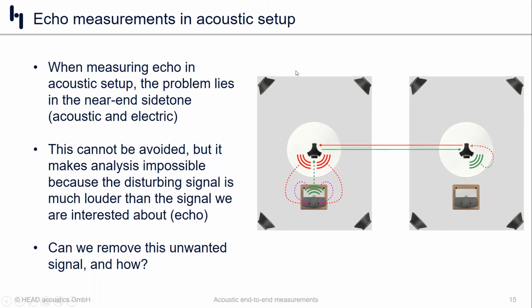So in this case, for the full acoustic end-to-end, we have 2 chambers set up. The process is the head and torso will speak, that's shown in green, to the device on the near end. We will send a signal to the far end, which will be playing out into the room, and sure enough, there will be some component of echo which is not canceled sufficiently by this far end device, which sends the echo signal back to us, and the echo signal comes out.